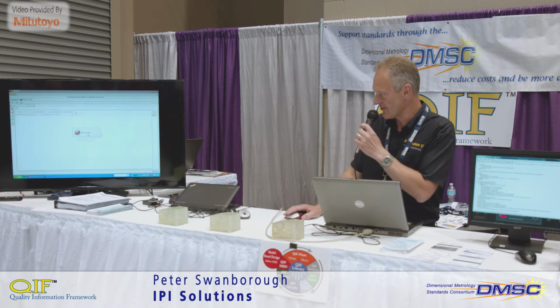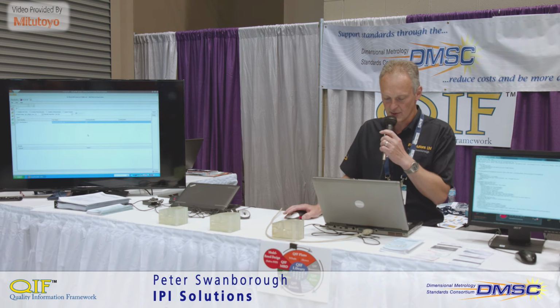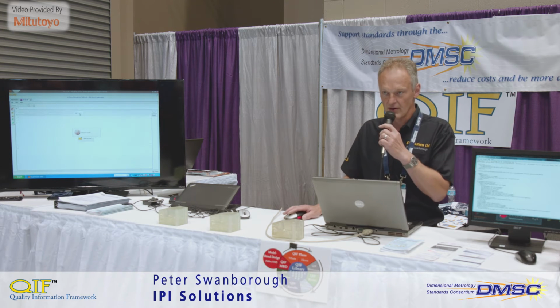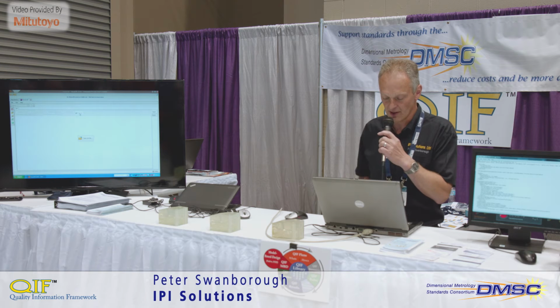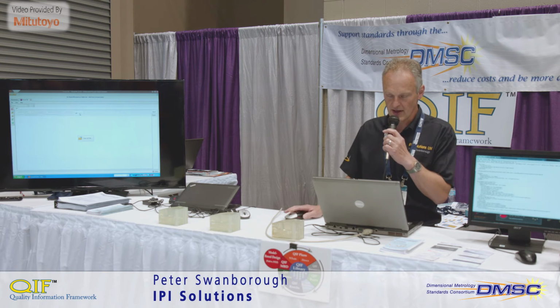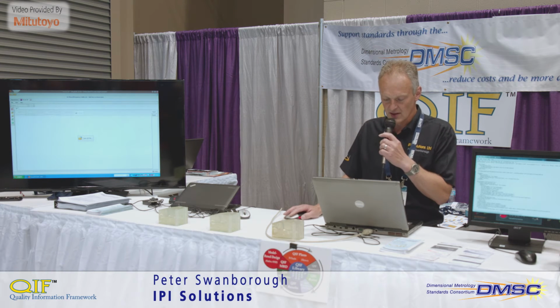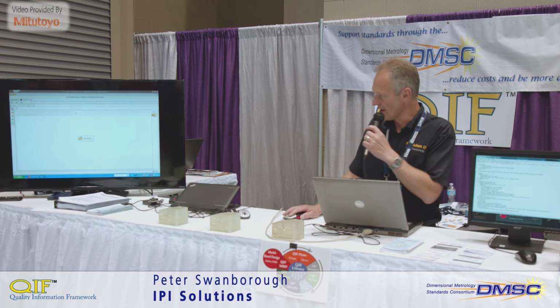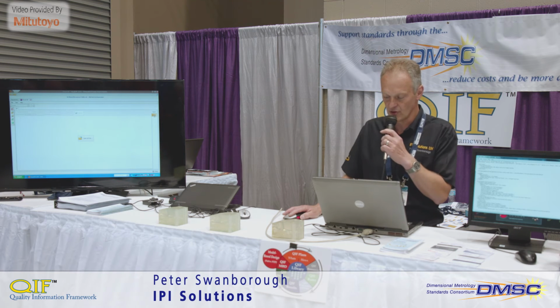Now, the reason that QIF is important to us: presently we can bring in results from most CMM devices, but there is individual unique programming per each device, whereas the QIF gives us a standard format. And QIF allows us to import results prepared by others, or we can export our own QIF file for consumption